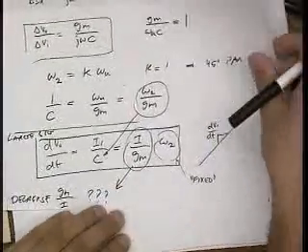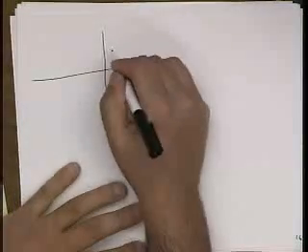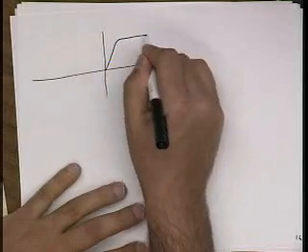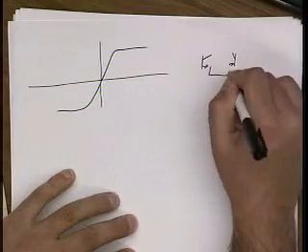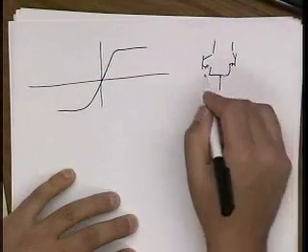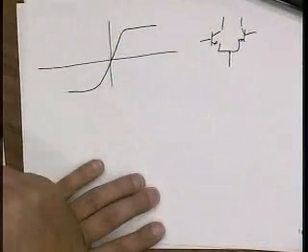And the reason that it's not a mistake is, let's say I take a bipolar amplifier, a bipolar differential pair. I know a bipolar differential pair has a really nice GM over I, right? Because of that exponential.